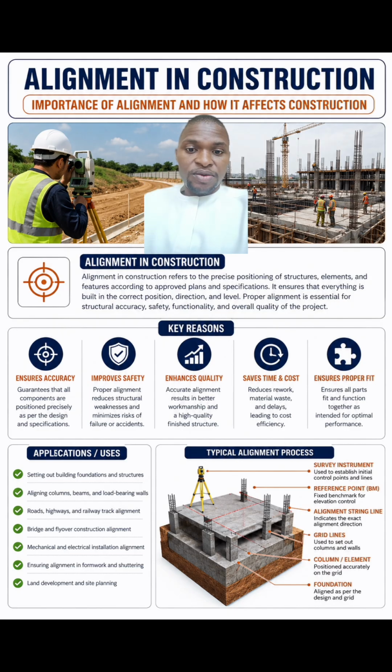Then ensuring alignment in formworks and shuttering. Yeah, during formworks, during your shuttering, alignment is also applied. Then land development and site planning. So during your land development, be it drainage, be it your culvert, be it any land development that you are doing, you need to make use of alignment.